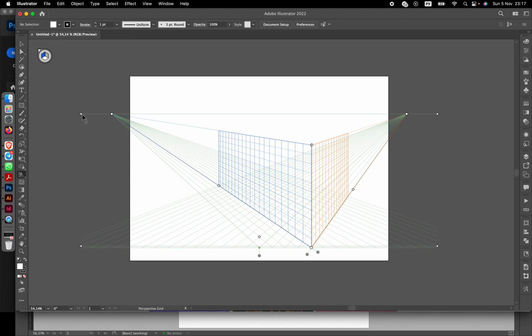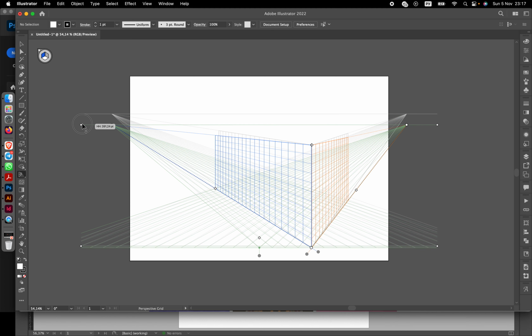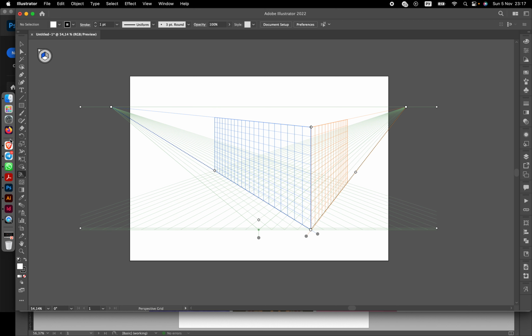And in this way, first of all, work with the navigation cube, select your rectangle tool, select the edge which you would like to use for the surface of the cube on which you would like to apply your rectangle, and start drawing your rectangle.